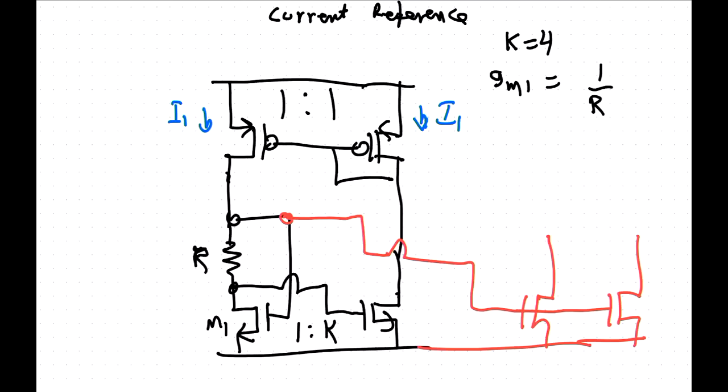So putting in a resistor, you really want something that's temperature independent, preferably. You can make that resistor out of a series of positive and negative temperature coefficient resistors to cancel the temperature coefficient. That is sometimes done. You normally have both on chip. It's quite common. So you can do that.